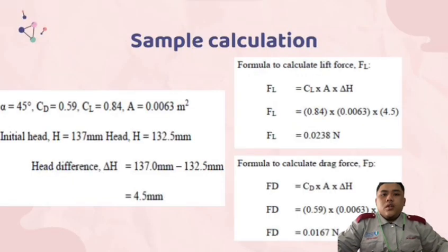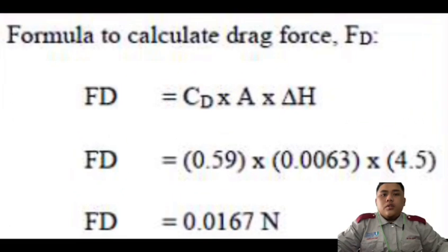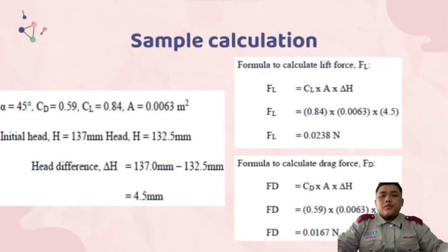For the drag force, it's the same formula as the lift force, but we will use the drag force coefficient. So 0.59 times 0.0063 times 4.5, and we will get the drag force, which is 0.0167 Newton.